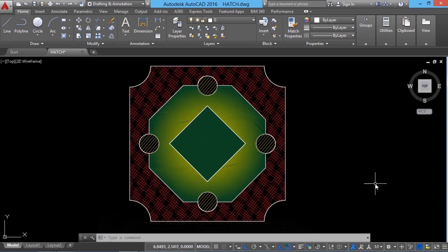In AutoCAD, you can temporarily suppress the display of hatch patterns using a command. For that, you can give the fill command. Fill mode can be in the on state or in the off state. Presently, it is in the on state. I'll just turn it off.